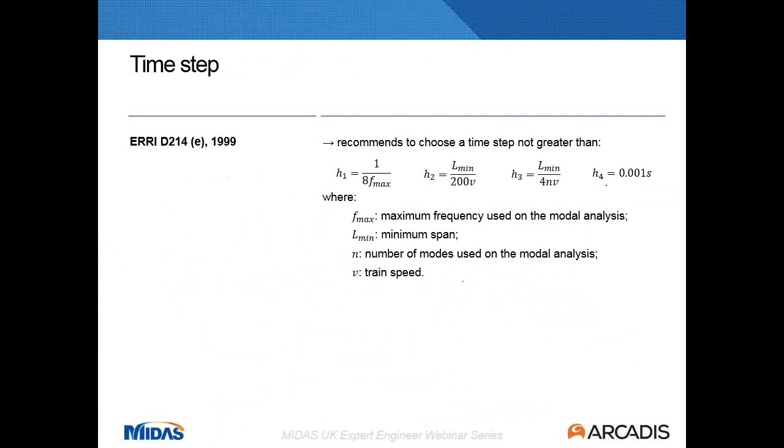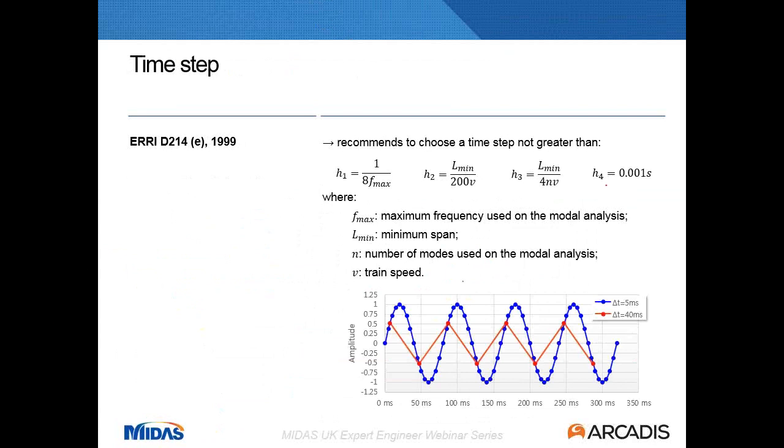Why is that important? Well, I've just added a figure here. In this figure, I'm just trying to describe the response of a structure, and I've run 2 different analyses. One with a timestep of 5 milliseconds. That's the blue line, and you can see that it is describing quite well how this structure oscillates and has a peak value of around 1.